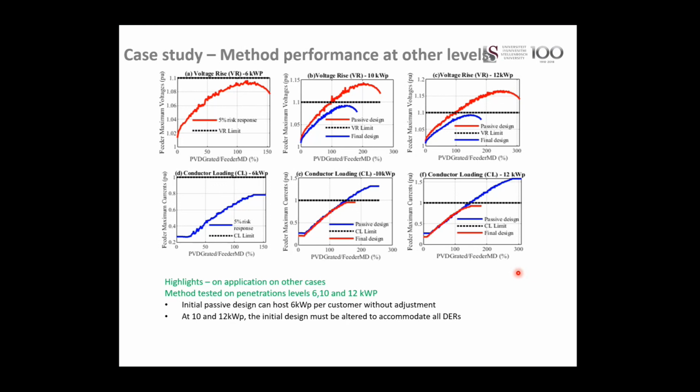So I think Marcus, and I don't know whether Neto is going to say the same thing, but what becomes a limiting factor on the distribution utility taking advantage of the DER on the feeder, whether it's on LV or MV, in terms of that voltage control mechanism? The biggest issue that I've seen is that these small scale embedded generators are rated as category A according to the grid code.